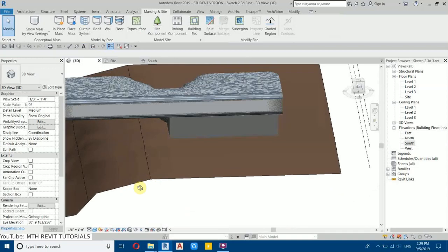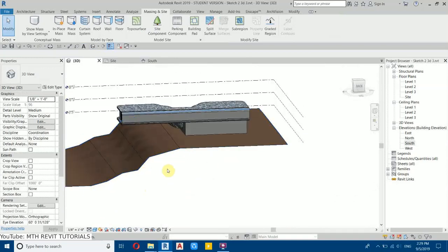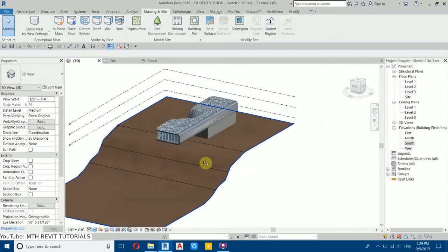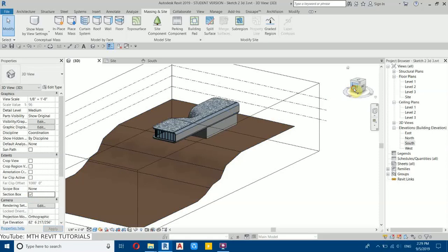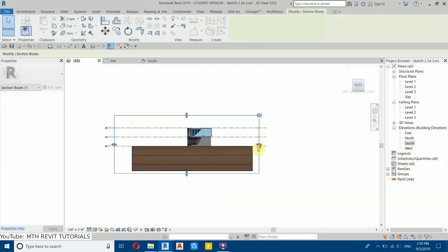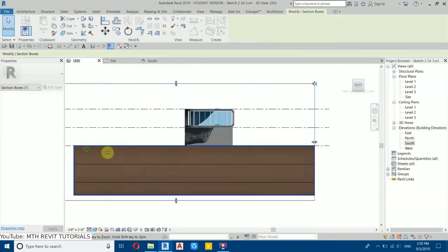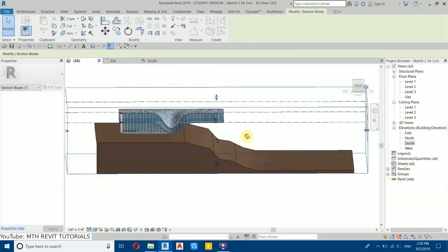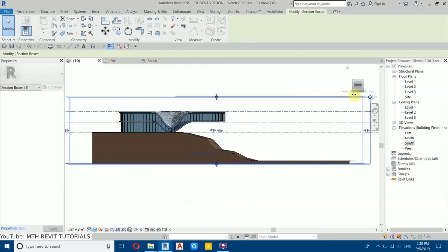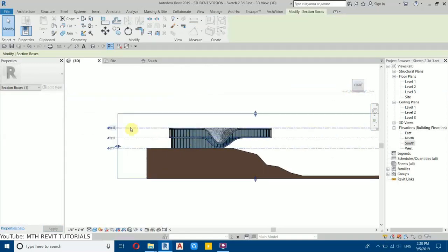You can see here it's just a thin layer. So if you want to show this part also, you need to turn on the section. So check this section box and then go to the right view and just cut some part of the topo surface on that side as well as on this, and just orbit around. You can see it's already showing that, and let's do that with the front and the back also, like so.